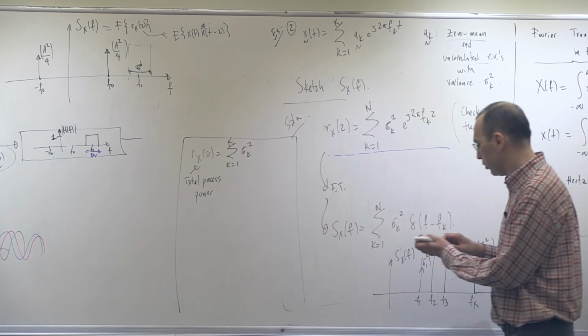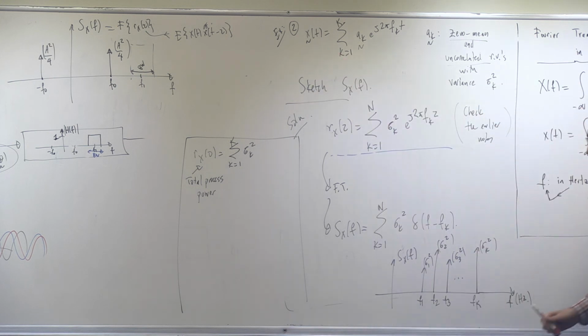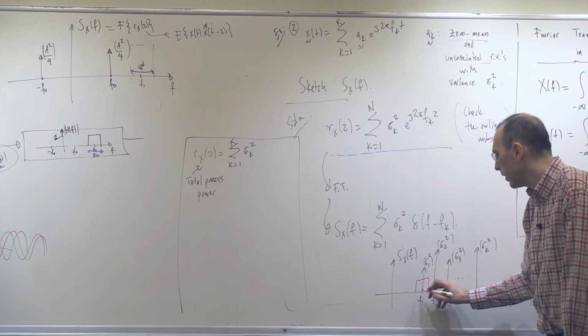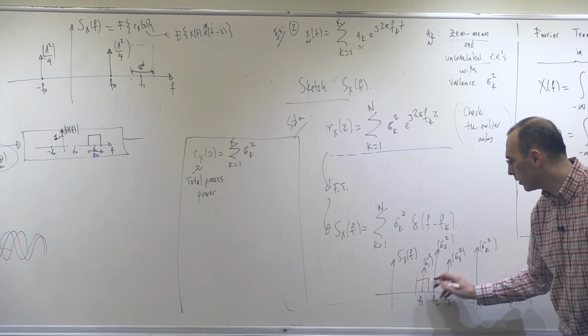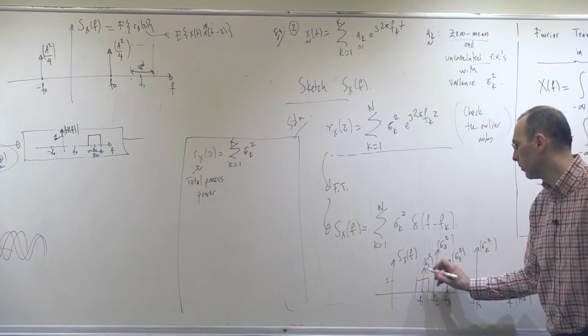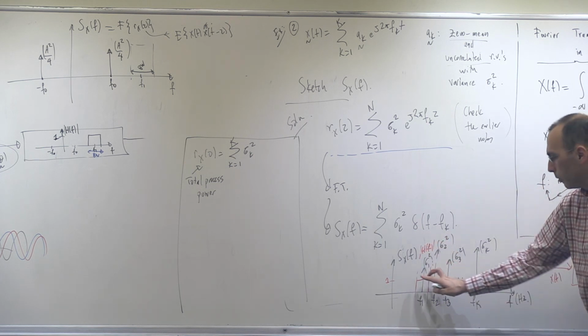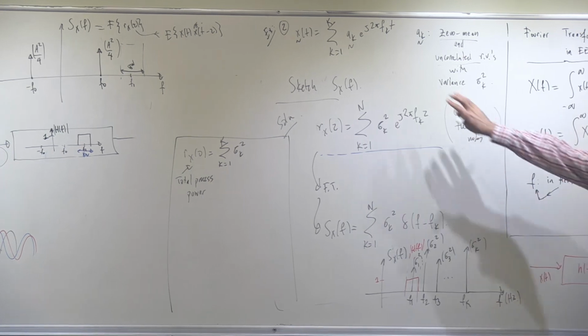So what do I see? Well, I see that if I put, again, this process, x of t, random process, through an LTI filter, and if that filter's passband contains this frequency, do you see what I mean? Now I have this x of t processed by an LTI filter, let's say h of t. At the output, you have y of t. If the magnitude response of this filter is something like this, 1, okay, so the red one refers to the magnitude response of this filter, then clearly this term will be passing through, and I'll be observing this much power at the output. Okay, so it will be, again, a filtering concept.